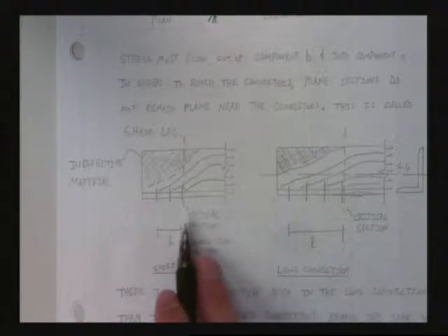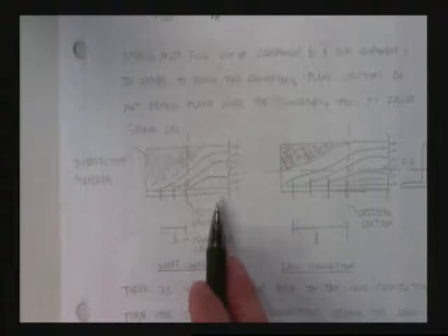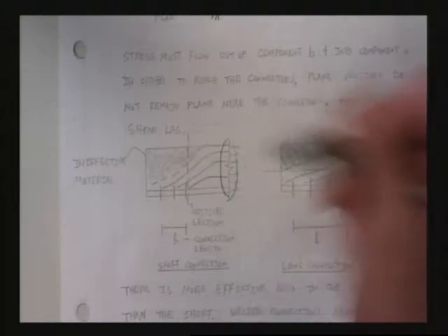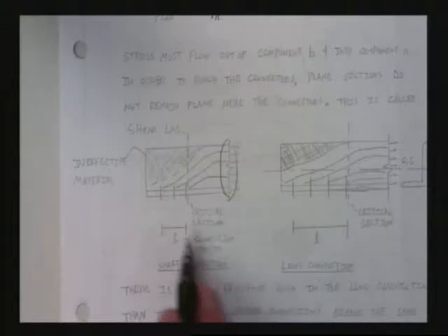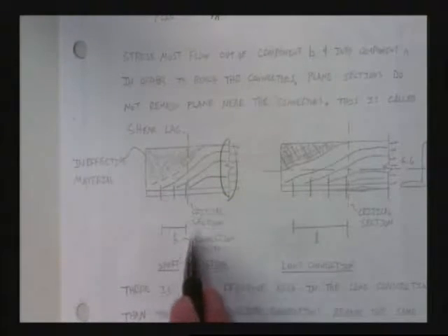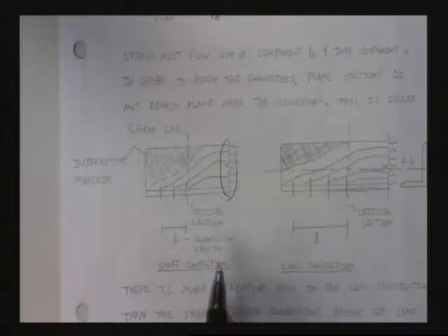Here, and this is what I've tried to show here. I've tried to show the exact same thing: what happens in every one of these connections is that here in this zone, and notice I don't have dimensions here, this is away from the connection. How far away? Well, a good number may be 2 times the depth, right? About 2 times the depth, or the depth.